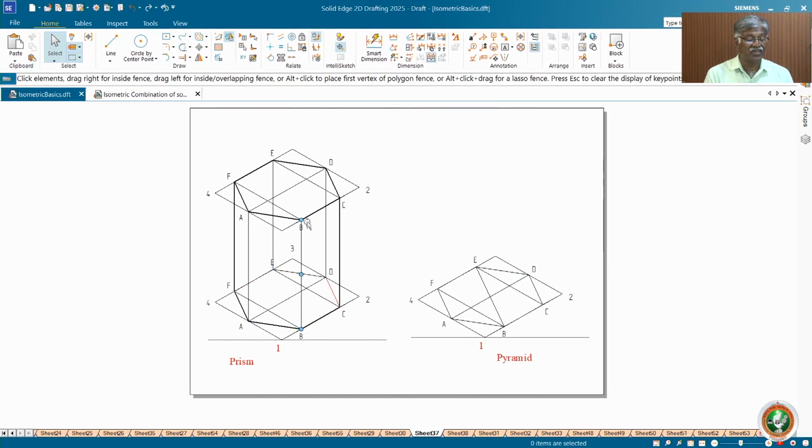Next comes this BB1, AA1, because they are crossing the invisible surface or crossing invisible lines. Definitely these are visible. Otherwise, start with bends, check with the crossing line, and also validate with invisible surface, visible line. Three checks are there for you.